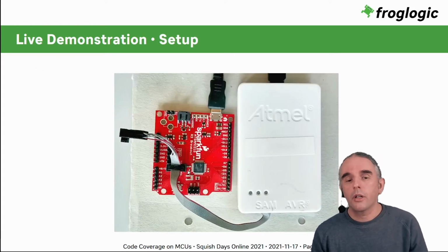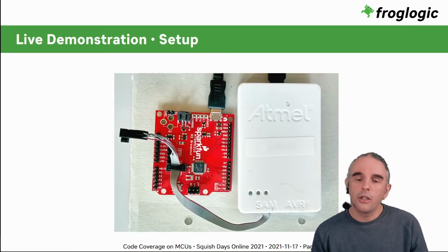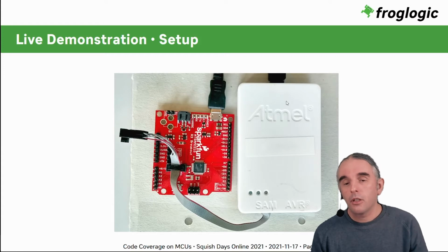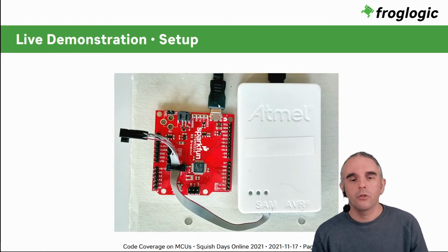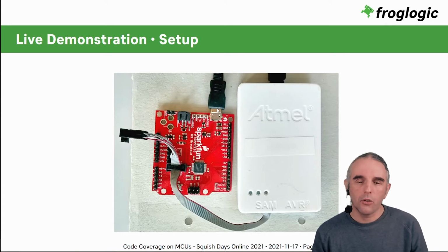So in order to connect this chip with a computer, you need some additional external hardware, and in this case we use Atmel ICE, and that helps us connect our development PC to this board. That's the way you actually write your program inside of this MCU. There are a few wires connected to this little electronic device, and then that device is connected to the PC. The USB connection which you see here is just for the power.